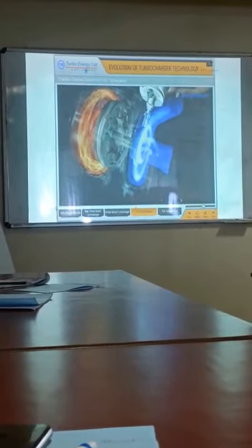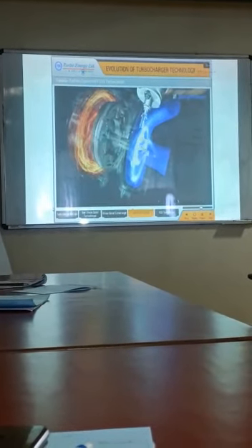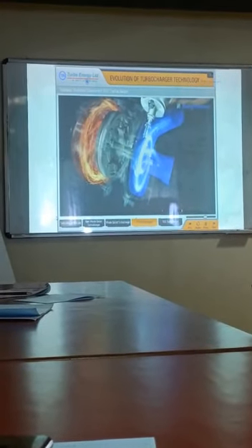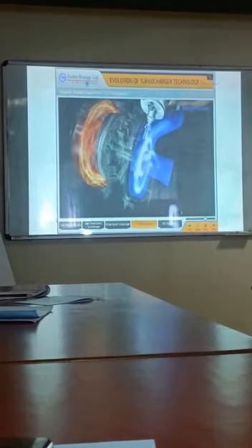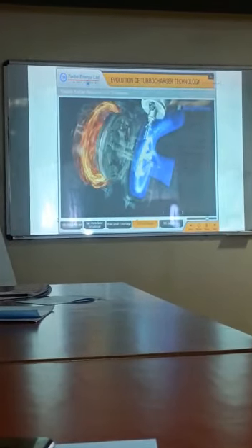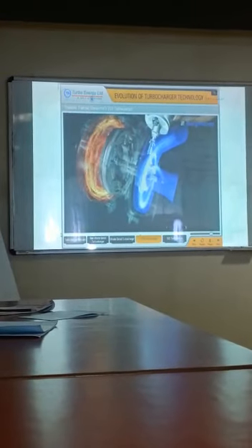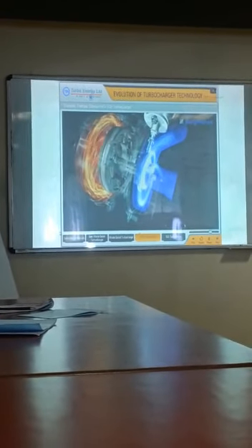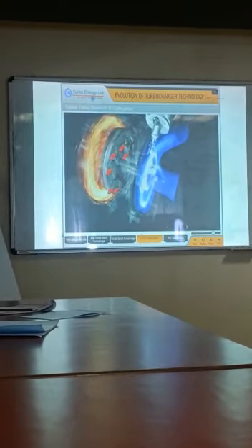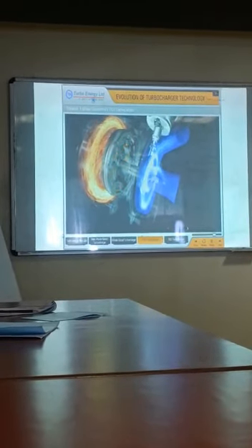All the vanes are connected to a ring, and this ring is connected to the actuator control rod. The actuator is connected to the engine vacuum circuit. The electrical switch operates the vacuum flow to the actuator, and the switch is operated by the engine ECU. We can see the actuator rod movement and the vane ring movement from the compressor side.